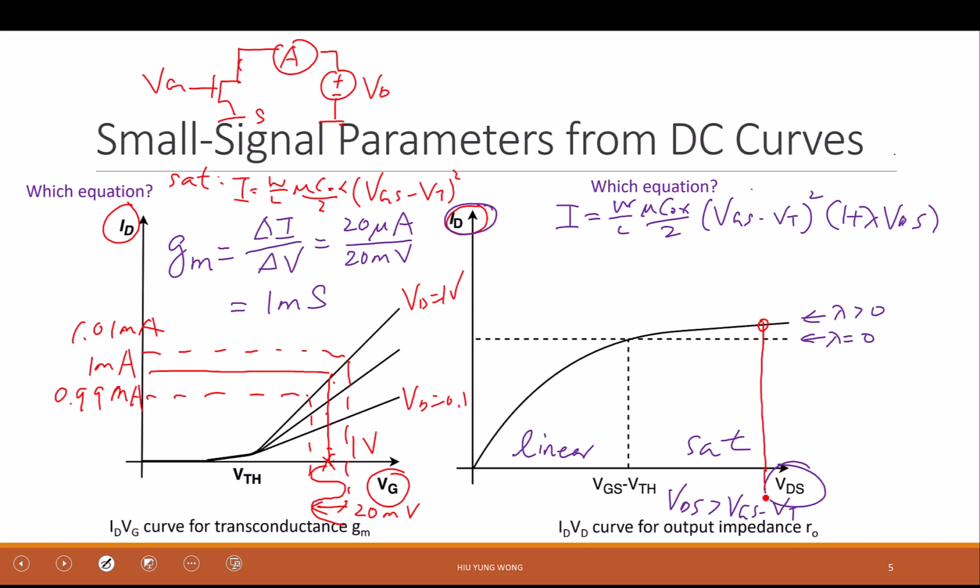Okay? And we can change the input voltage, right? You can call it input or output. We change the VDS. Again, maybe I change it by 20 millivolt peak to peak. I do the same thing as I did for the VGS. Then in that case, what will happen to the output current? Well, it's going to again swing about this line, right? My drawing is going to be very bad, but you know what I'm talking about here. It's completely off, right?